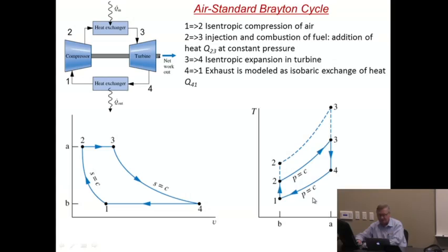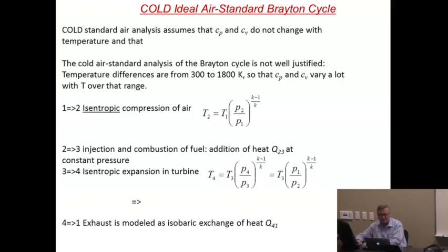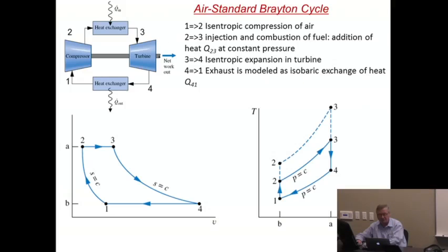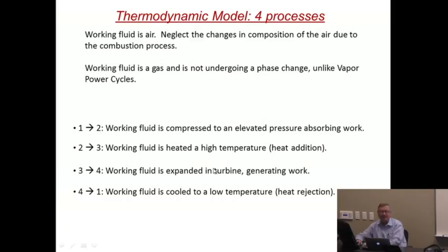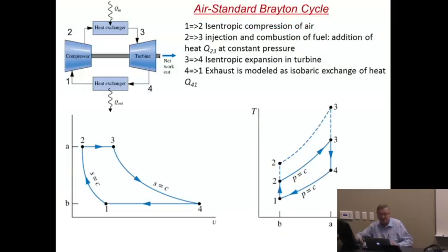Well, so that really can be done in two ways. Well, I lost that graph. That cooling step can be done either by releasing the air outside, and then you will assume that the temperature of the air after a while outside is going to be the temperature of the air at the intake, or it can be done by recycling the turbine exhaust, like in point number 4, through a heat exchanger, cooling it further and sending it back to the compressor.